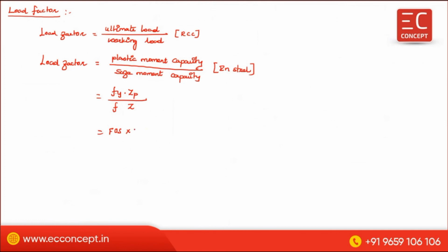ZP by Z we can write as the shape factor. Therefore, the important relation is load factor equals factor of safety into shape factor.